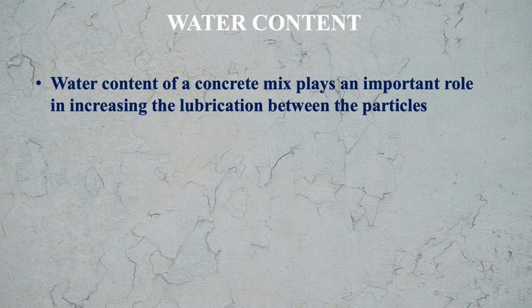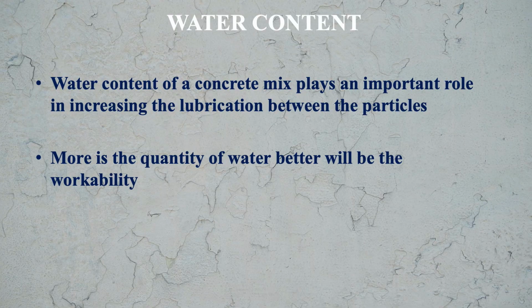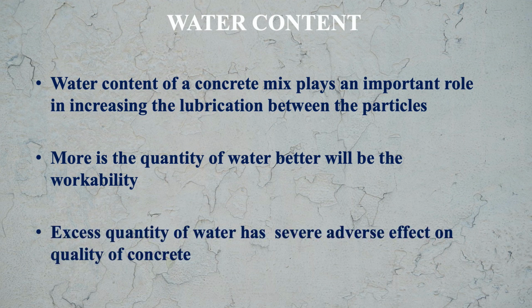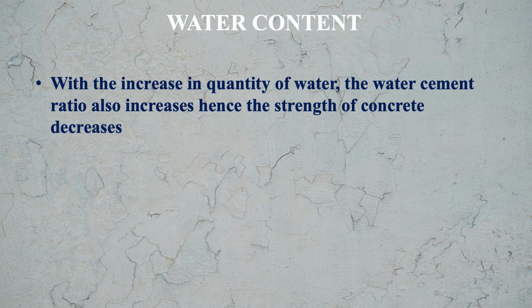Water content of a concrete mix plays an important role in increasing the lubrication between the particles. So here the role of water comes into the picture, that this water can act as a lubricant between the particles, and more is the quantity of water, better will be the workability. But excess quantity of water has severe adverse effect on quality of concrete. With the increase in quantity of water, water-cement ratio also increases, hence the strength of concrete decreases.